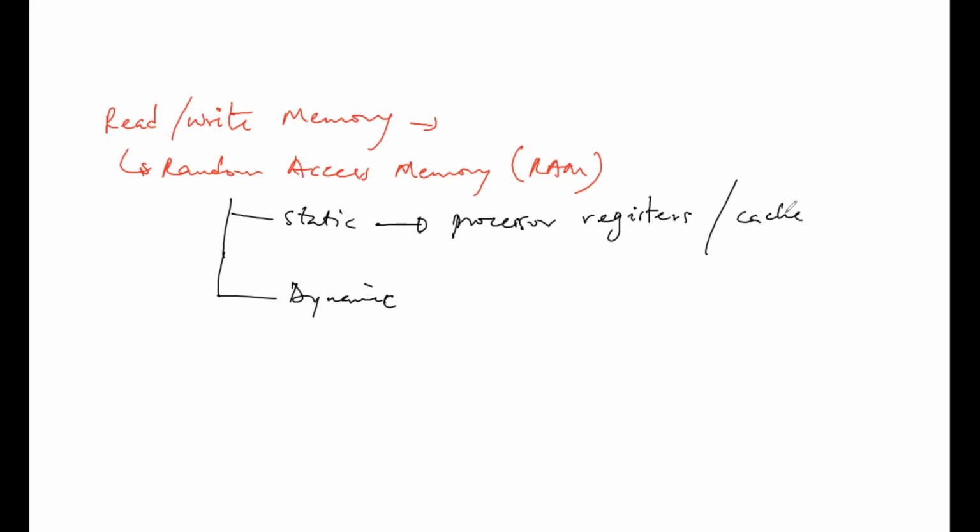Now for the dynamic RAM, which is the DRAM, this is SRAM. Then for the DRAM, it's actually a complex memory device that uses a tiny capacitor to store bits. So here we use a capacitor in terms of design. A charged capacitor represents 1 bit. Since capacitors slowly lose their charge due to leakage, they must be refreshed periodically to replace the charges representing 1 bit.